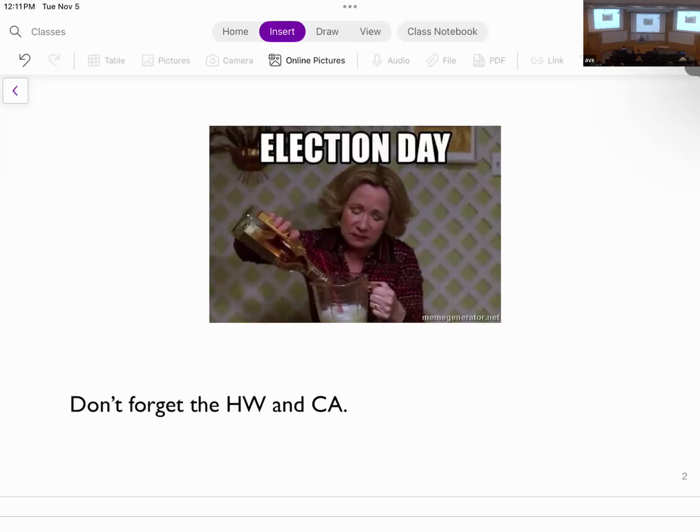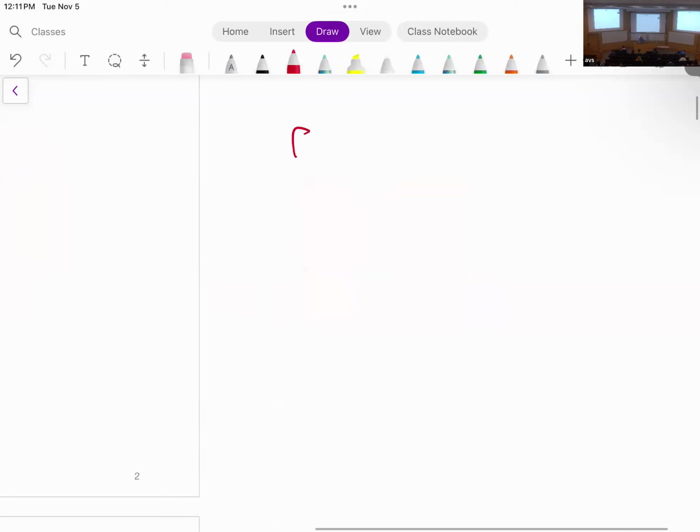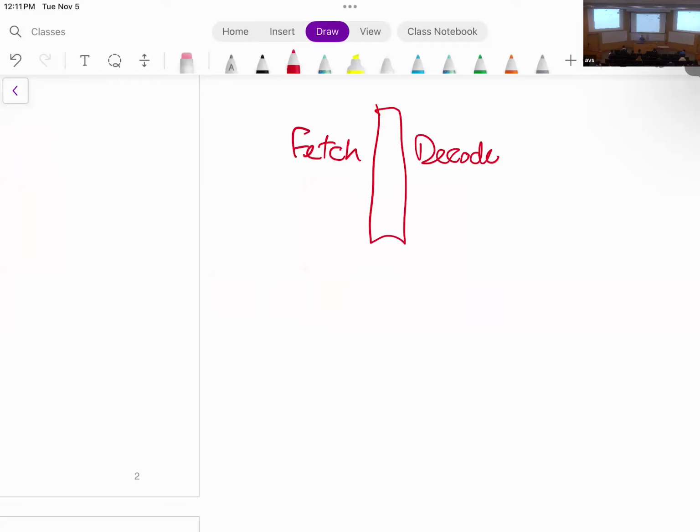The second thing is that if your processor needs to be stalled, an out of order processor typically works this way: you have a fetch, and then you have the decode. Usually there is a pipeline register in between them, what we call an instruction queue. Since this is, for example, a superscalar processor, the fetch grabs 2 instructions and puts them into the instruction queue.